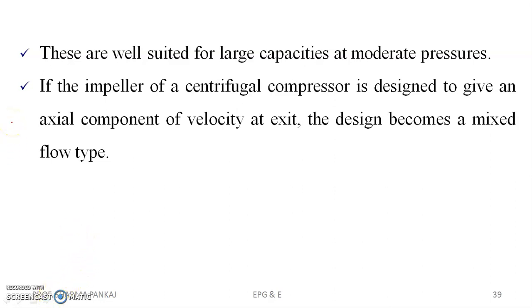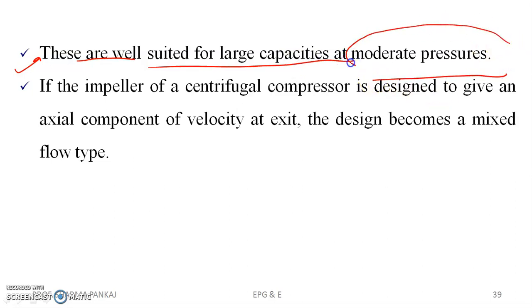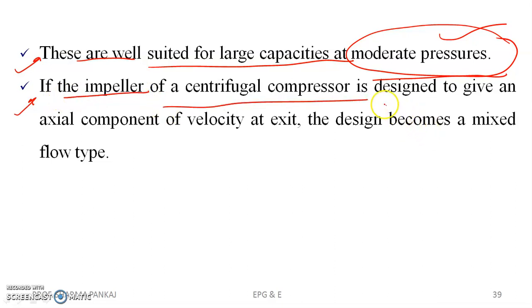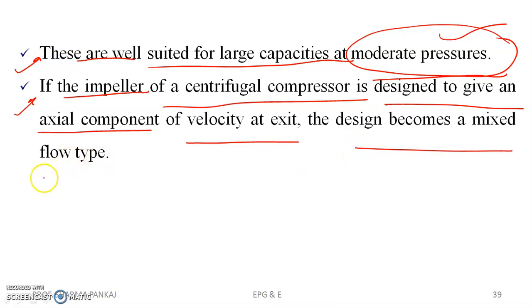These are well suited for large capacities at moderate pressures. If the impeller of a centrifugal compressor is designed to give an axial component of velocity at exit, the design becomes a mixed flow type.